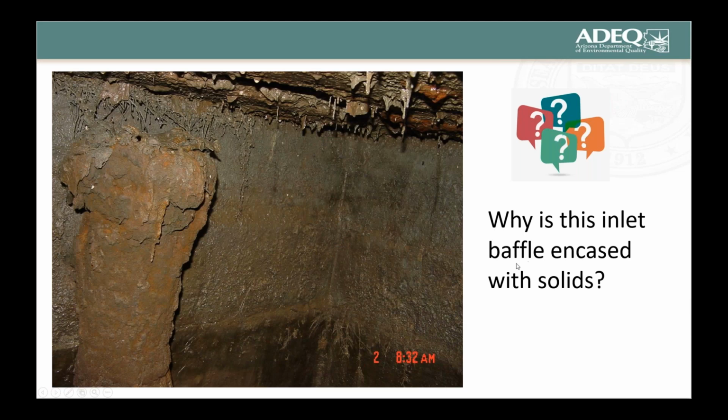Now, why is this inlet baffle encased with solids? If the outlet is not able to carry the flow away, then there's going to be a backwater effect. The scum would rise up and over the top. Another thing is the scum layer just built up and it was never pumped. My father-in-law was very proud of the fact it had been like 20 years and he'd never pumped a septic tank. But maybe somebody had that same idea here, that they could go 20 years and never worry about their septic tank, only they had a problem.